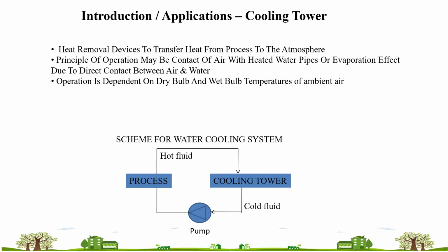Why? Because dust particles fall into the cooling tower basin. But the air quantity required for better performance is then not provided. So that's how critical the location of a cooling tower is.